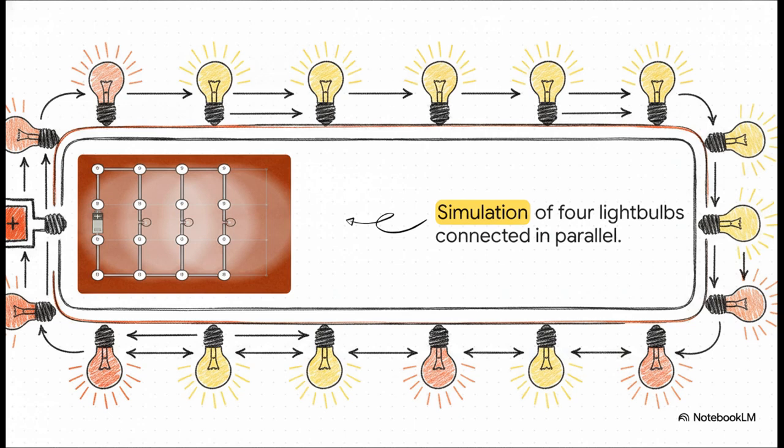If we expand this logic to a simulation of 4 distinct bulbs, it visually proves exactly what we just calculated mathematically. Basically, the more parallel paths you add, the more overall current gets drawn from the source. Your battery is forced to supply the sum total of whatever each new branch is demanding, which means, theoretically, if you had infinite branches, you would need infinite current. It perfectly illustrates this direct, unavoidable relationship between the size of a network and its total power draw.